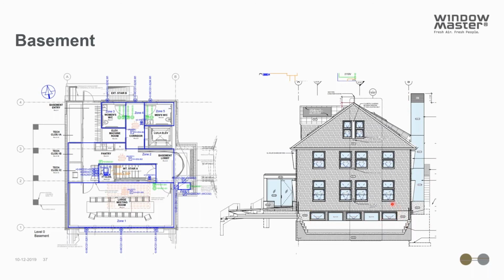But again, if you have a meeting area where you just have the option of single-sided ventilation, then it will be very difficult to provide a high enough ventilation rate to comply with the high density of occupants in this type of space. So in this solution, it was solved with a thermal chimney, which goes very well with the design of the house, you can say. And this is maybe something that would be another solution in a more traditional office design.